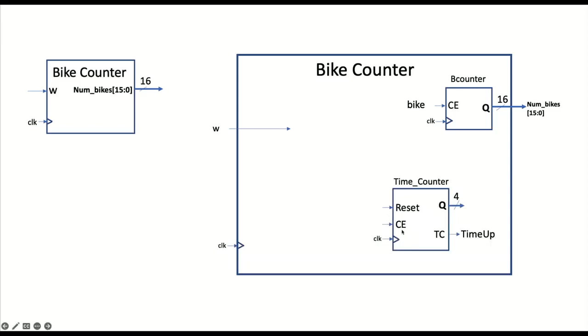Okay. And then, but I need to make sure this counter starts at 0. So I'm going to need to be able to tell it to start now. But I can just let it count. So this counter counts all the time, every clock edge. But when I need it to be 0, I can reset it to 0, so I can make sure that I start at 0 when I care about the count.